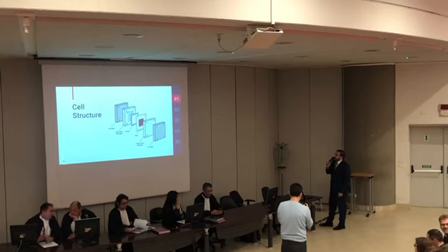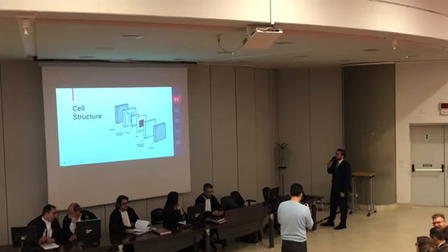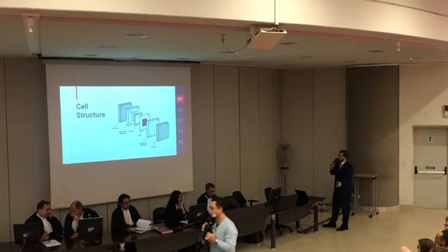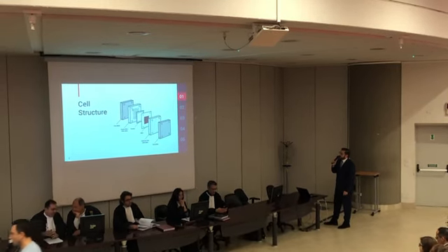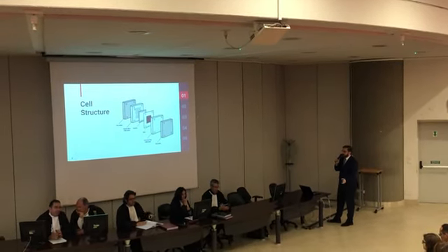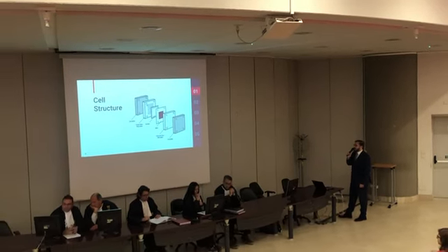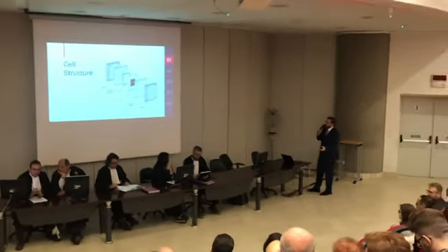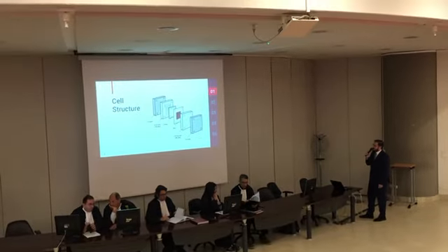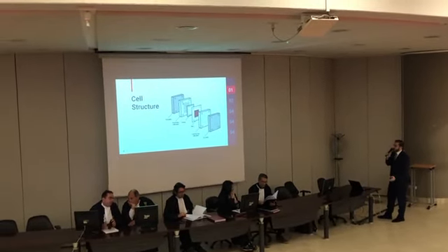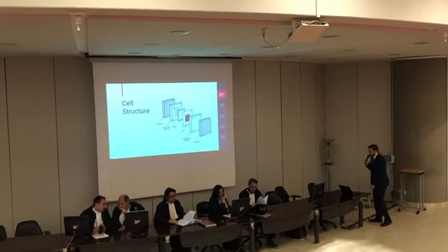In the figure is represented the structure, which is mainly composed of several layers. The innermost layer allows the separation of the hydrogen into protons and electrons. Then the gasket prevents the leaking of gas inside the cell. The anode and the cathode flow field plates allow the electrical conduction between the two plates, and the end plates have a structural function.